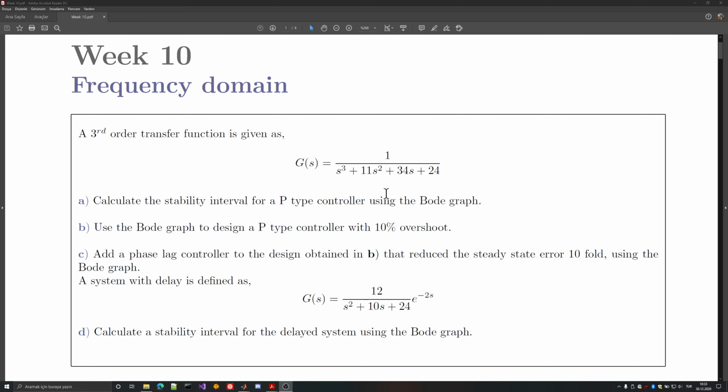In the laboratory, as I've said before, you apply some sine waves, and you are observing the sine waves in the output, and then working out the difference in terms of gain and phase will give you basically two simultaneous plots that are on top of each other, which represents the Bode plot. Of course, I'm telling you that this is a laboratory approach, but since you have the model of the system, it's even easier. You don't have to go into the laboratory and use the system. You can also use this mathematical representation. Namely, if you plug in j omega, you will get a complex valued function that has a real part and an imaginary part. As you know, this is a Cartesian approach. If you change it to polar coordinates, you will get basically what you will be needing for the Bode plot, since you need a gain, which is the change in the gain of the sine waves from input to output.